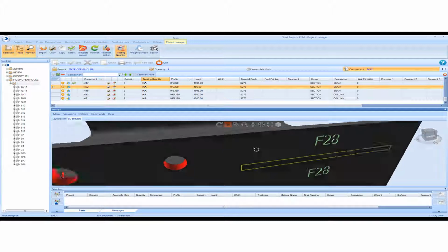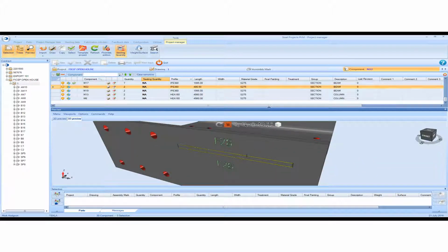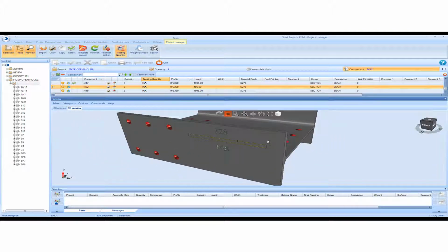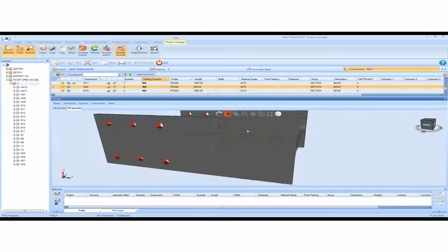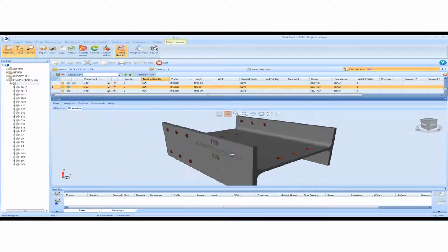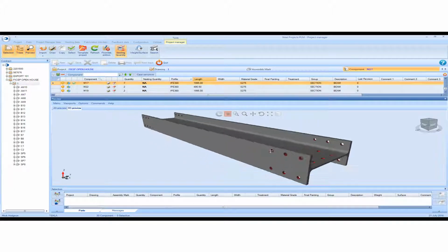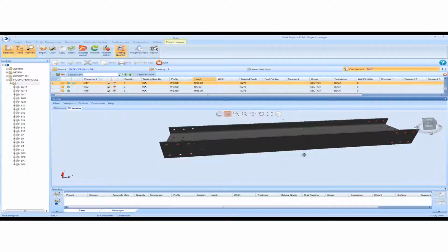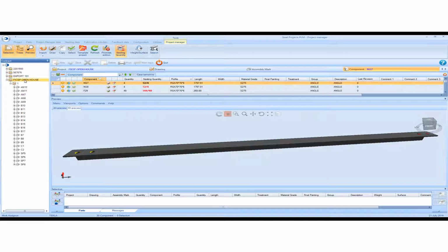If you zoom in, you can see the layout information, the marks of the piece that's connected, so that's the plate that's connected to the beam, and the scribing or layout of how that piece is fit together. So the machine will actually mark and show the fabricator how those pieces go together without any manual layout whatsoever. So simple enough process, just a few more examples and a few little walkthroughs.